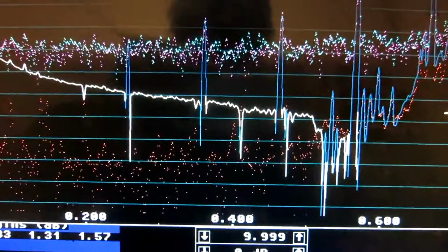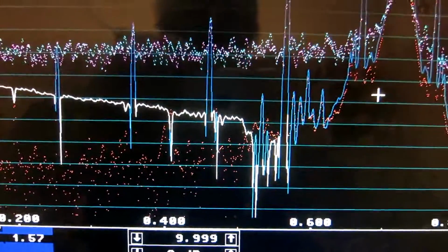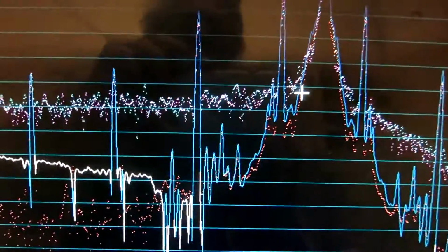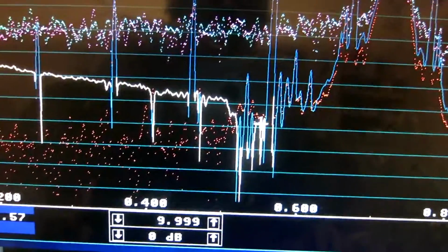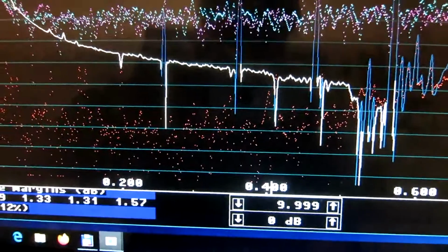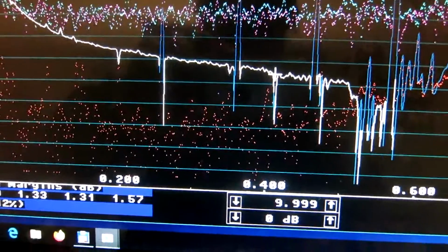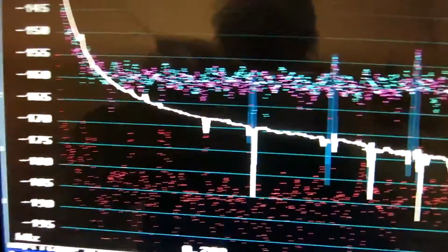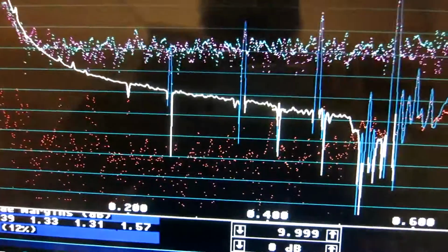And here is the AM noise. It is more favorable. It means that the contribution from the center is smaller, and at 400 Hz it doesn't have any effect on what I can read. So what I see here is minus 172.5 approximately.